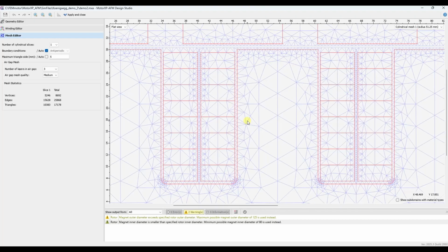Let's say in case that you want to simulate instead of a sine wave input, you are inputting a current with a certain switching frequency coming from the power converter, and therefore you want to understand the eddy currents on the edges of the conductor, and therefore for that you need to have a skin depth mesh. So it's not just being a thin mesh; it's a skin depth mesh, which is a different feature. Is it something that you can do now, or eventually that you can think about for the future? Just let me show you something. Yeah.